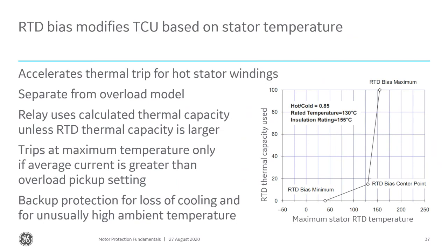So just because your thermal capacity is at 100% does not mean that the relay will trip unless you set it that way. It won't trip for overload. Got to keep that in mind. The overload and the thermal capacity are two different things.